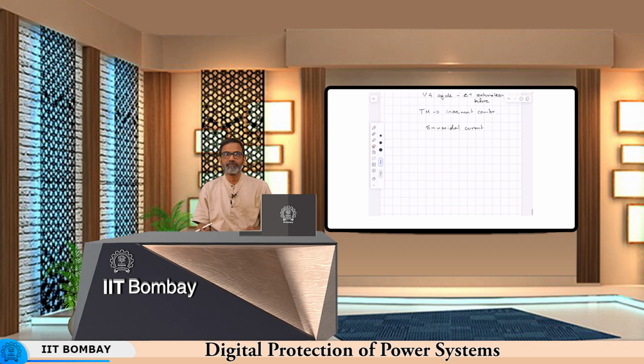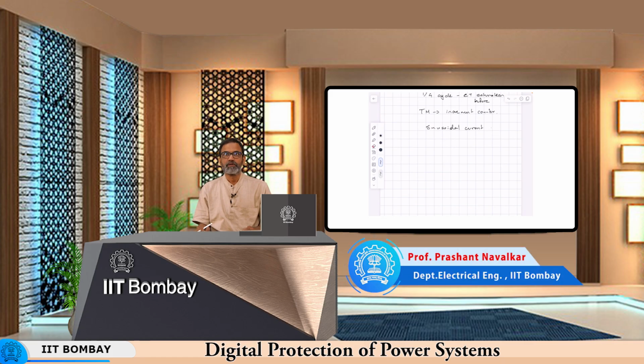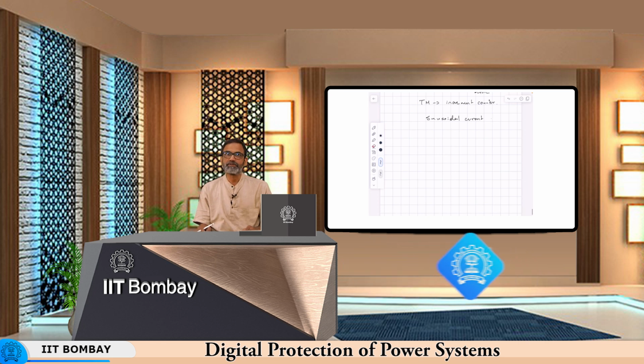So, in the last lecture we looked at bus bar differential protection. Today we will look at transformer protection. Transformers, as you know, are devices which made AC transmission possible. In fact, the very first transformer was a Scott connected transformer. The first generator transformer was a Scott connected transformer, 2.2 to 22 kV, and then 22 to 11 and then 11 to 2.2 on the consumer side.